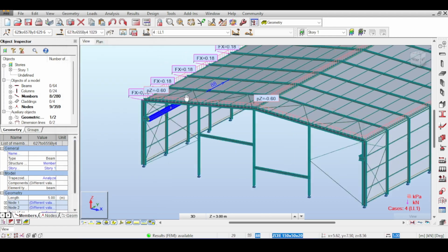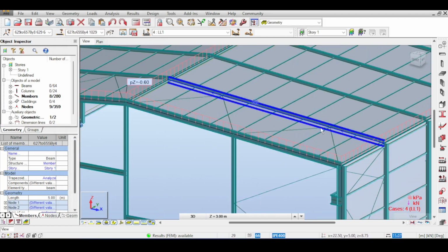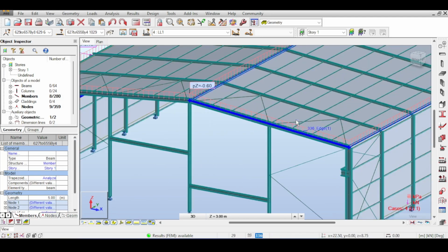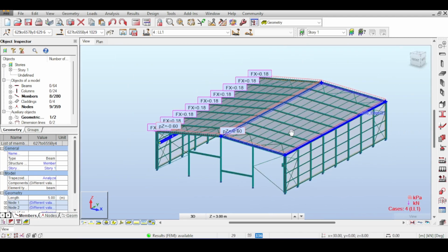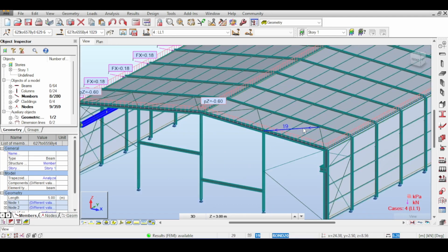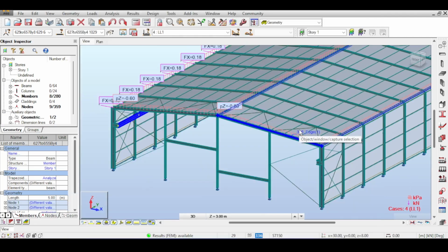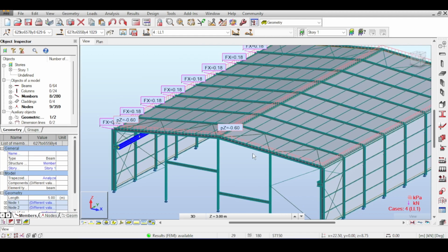And the third thing was about having bracings that are compressive. And believe it or not, those do exist. Now, I went to IKEA specifically to see that in action because I wanted to make sure that whatever I say here is happening. Of course, the bracings usually are tensile in nature, but you can have compressive bracings, and sometimes you have full trusses as compressive bracings. And I'll just show you some pictures here about IKEA from the internet, something I've seen in my own eyes, where they actually use heavy-duty elements that are compressive resistant in the stabilization of their frames, which is really cool.